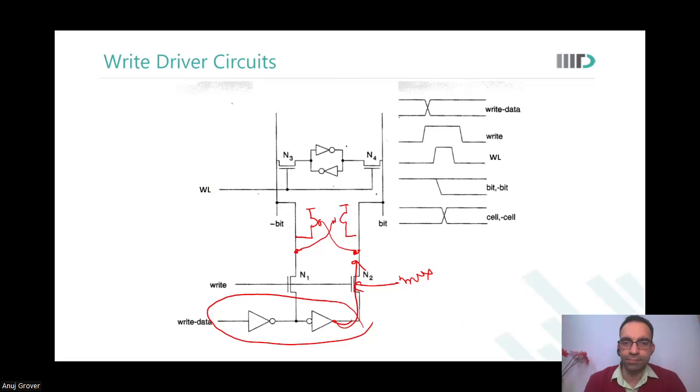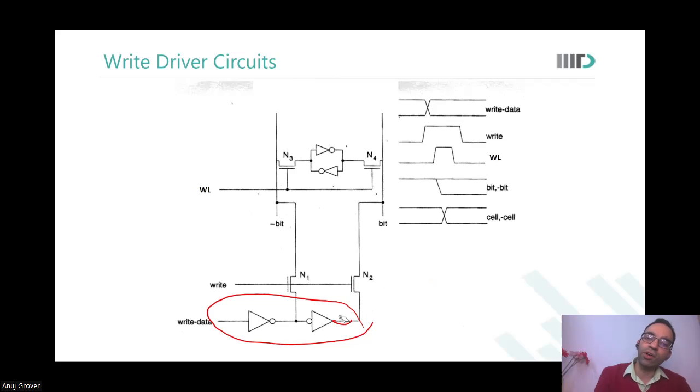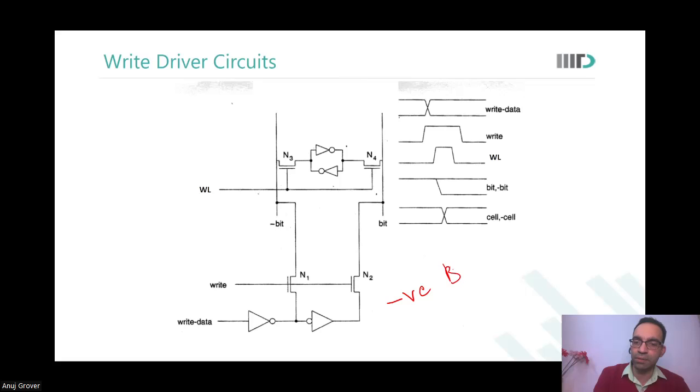Yes, sir. So there are multiple ways to handle this. So this circuit was incomplete in itself. You are absolutely right. We needed some semblance of a transmission gate, or we needed a cross-coupled PMOS like this. In addition to this, we already talked about write assist schemes. So when you design the write driver, you also need to design circuits so that your bit line can be taken to a negative bit line level, so that you can have negative bit line write assist scheme.